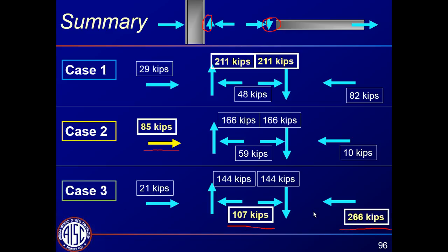So you could either design these joints for both case 1 and case 2, or you could, if you wanted to, take the maximum vertical force and combine it with the maximum horizontal force. That looks like it'd be a bit conservative here, and it certainly wouldn't be required.